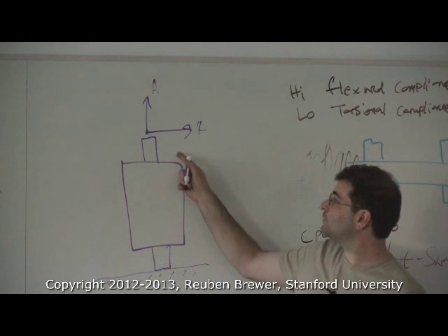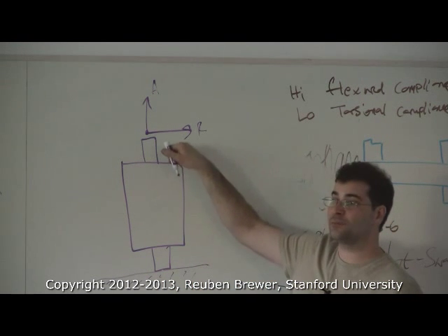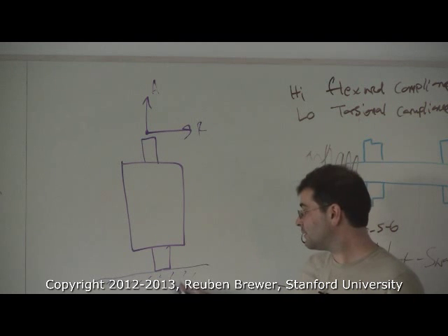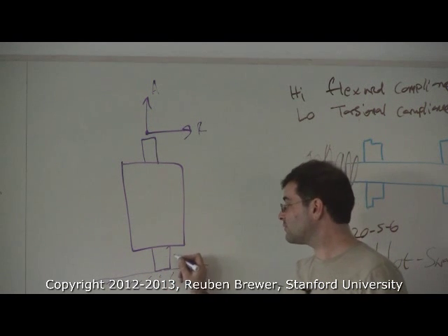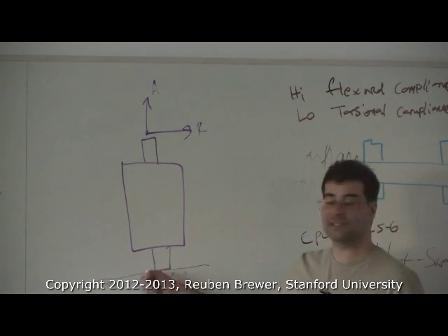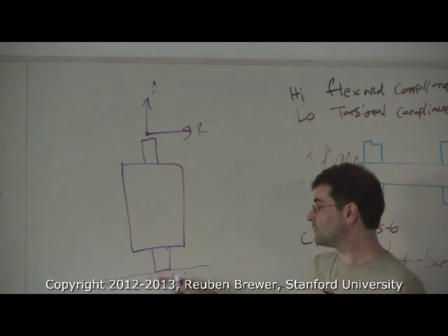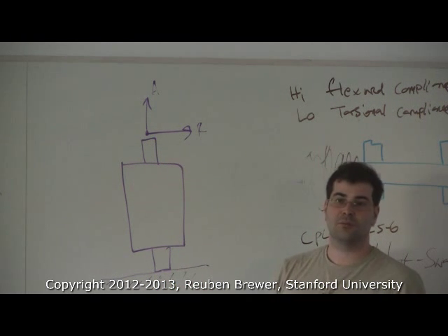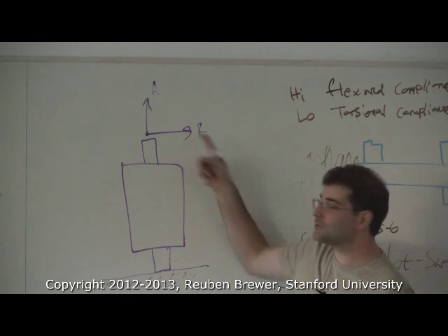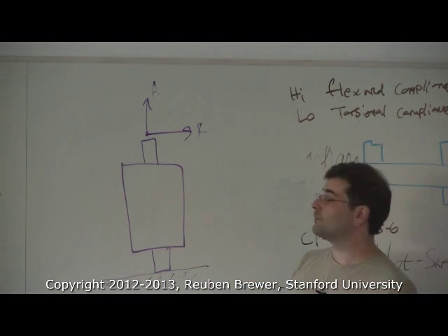Okay, now that's just for installing. What happens when you take your press fit off? Now we can't use this trick. Now we have to grab onto that, and grabbing onto the back shaft is even harder than grounding it. So just don't press fit. It's bad. It will kill the bearings in the axial direction.